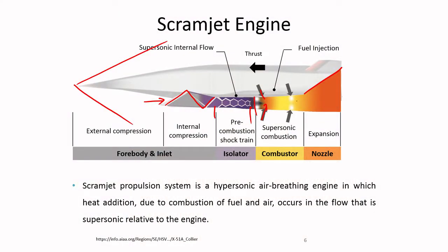And the other thing is that yes, we call this portion the combustor, but the combustor is very intricately related to the inlet, where we have external compression of the external flow, where you have internal compression, and then you have the isolator, and then you have the nozzle. So, the whole thing becomes very coupled, and because there is no rotating machinery which can be controlled by the operator, the combustor also encounters a wide variety of flow and thermodynamic conditions.